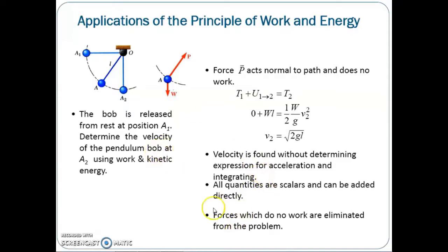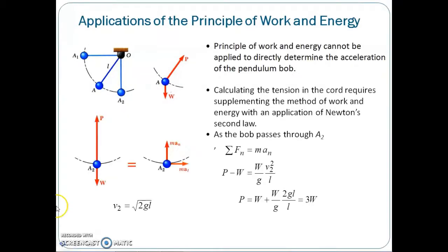So those forces which do not do work are eliminated from the problem. So it becomes easier when we are dealing with problems involving forces, displacement, and velocities. However, the work-energy method has its limitations. For instance, the method of work and energy cannot be used to directly determine accelerations.